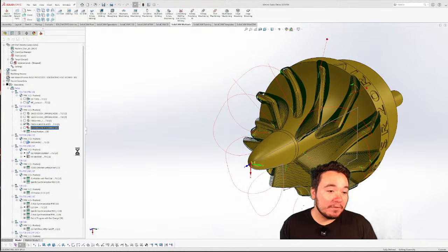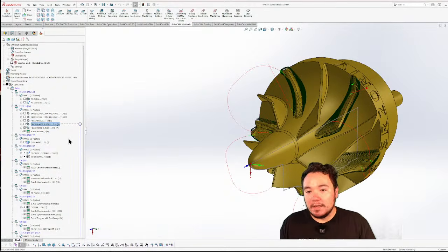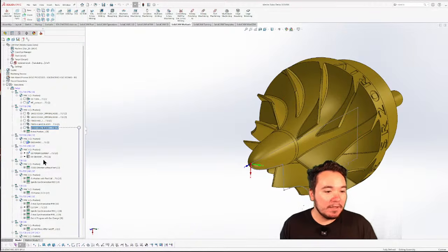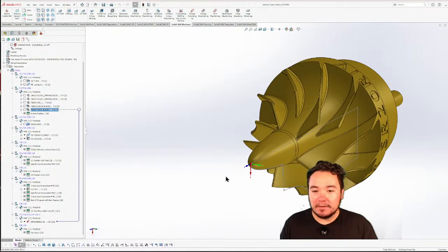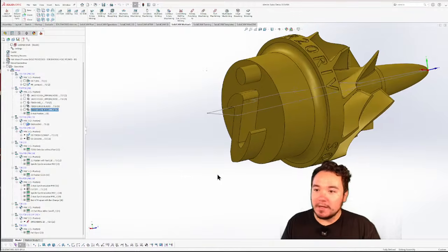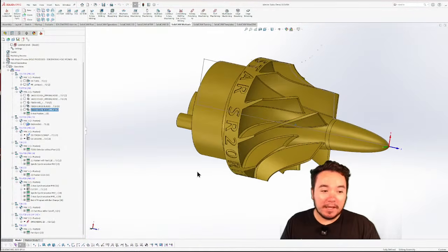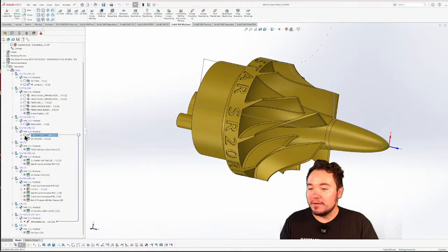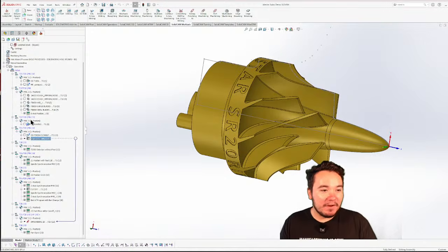And this is all pretty small tooling. You'll see if you go to West Tech, I think 2mm is actually the largest end mill we're using. And 1mm is going to be our finishing ball end mill, and then we're also doing some iMachining on the back side here, and that's going to be a 1 millimeter square end mill. And again, it's going to be really impressive at the show. I can't wait for you guys to see it. Maybe we'll include some clips of it in our next night class as well, so everybody will be able to see it.